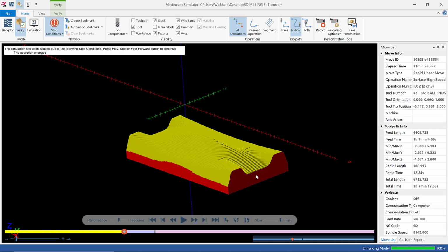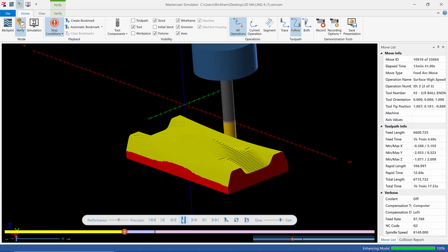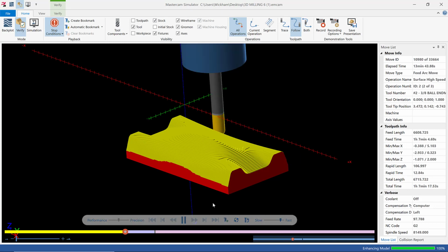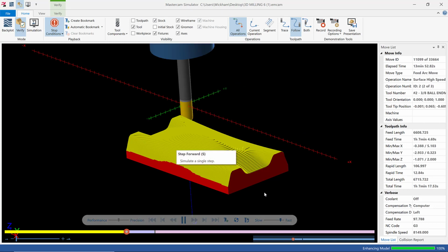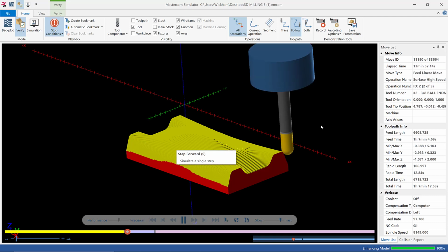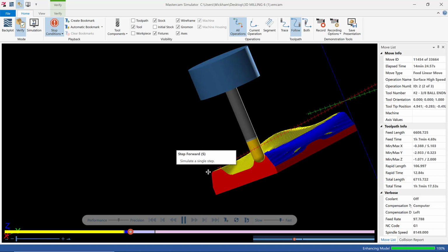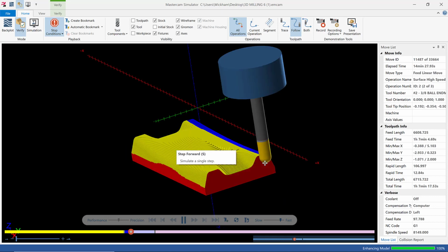Alright, there is the roughing. I'm going to let it finish up there. Again, patience with this is going to help. I usually give it a couple minutes to make sure the little blue circle next to the mouse icon goes away, then hit play and let it go through its semi-finish. It is right now. Looks like it did before, so that's good.